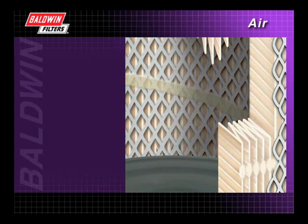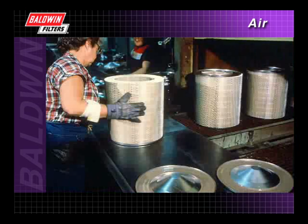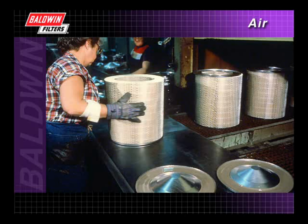In situations where larger filters require deep pleats, or where there is high pulsation or direct side inlet flow, Baldwin applies a special hot melt beading to lock the pleats in place and prevent bunching or excessive pleat movement. The final step in Baldwin's air filter construction is the application of a special potting compound to the end caps. This compound bonds the media pack, which includes the inner and outer metal wrappers, to the end caps, forming a strong, rigid package.